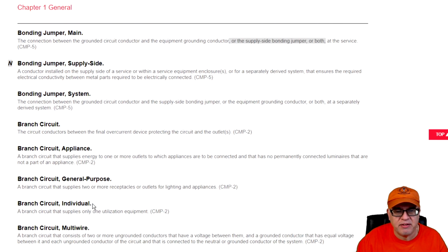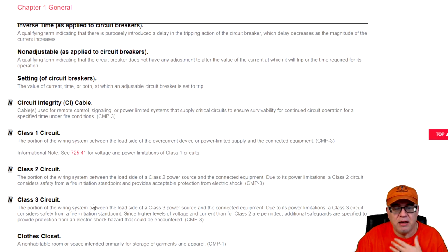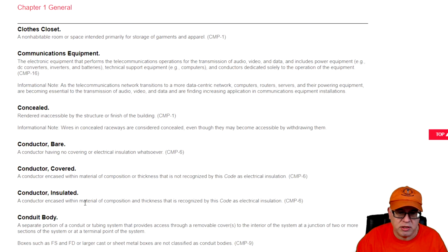It's kind of how you put these things together and how you work, and it might make the difference in understanding and applying the National Electrical Code, okay? But if I conceal something, even a raceway behind the wall, then it's considered to be concealed as well, okay, for the wires that are in that raceway.